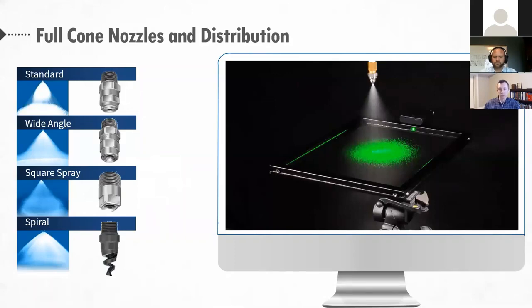So yeah, there's certainly some differences, but a spinning disc can provide, like I say, larger droplets, wider pattern, and a very consistent droplet size. But typically, so to go back to the question, a hollow cone I would expect to have a smaller droplet size typically.